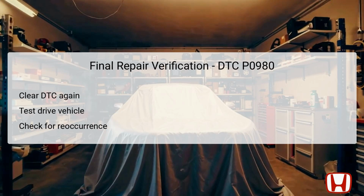Following successful repairs, it's vital to verify the integrity of the entire system by clearing the DTC using the HDS. After clearing the code, the technician should proceed with a road test under varied driving conditions to ensure the vehicle shifts smoothly without any interruption. This test drive will help confirm whether the issue is resolved and will validate the repairs made.